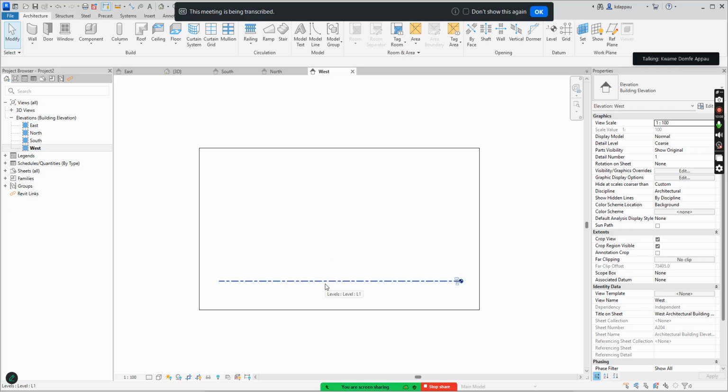Then we have another set called content. The content is either 2D content or 3D content. And then the third thing is the views and then the sheets for representation. So you need the datum elements to be in place before they can have content. Without datum elements, there cannot be content. Do you understand? And without content too, there wouldn't be the need for views and then for sheets. So in the first place, we must understand how we work with the datum elements first.